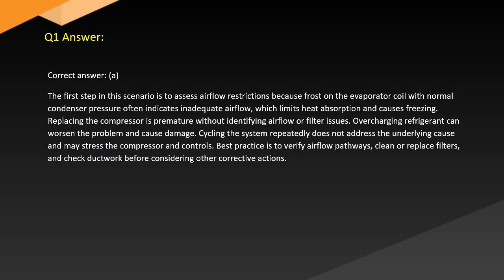Answer. Correct answer. A. The first step in this scenario is to assess airflow restrictions because frost on the evaporator coil with normal condenser pressure often indicates inadequate airflow, which limits heat absorption and causes freezing. Replacing the compressor is premature without identifying airflow or filter issues. Overcharging refrigerant can worsen the problem and cause damage. Cycling the system repeatedly does not address the underlying cause and may stress the compressor and controls. Best practice is to verify airflow pathways, clean or replace filters, and check ductwork before considering other corrective actions.